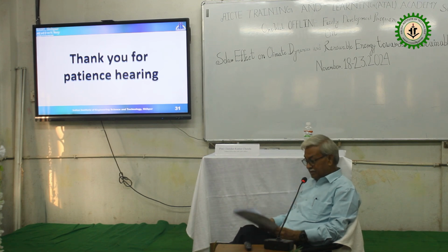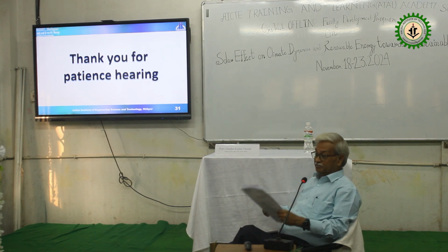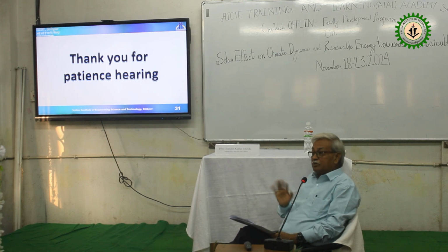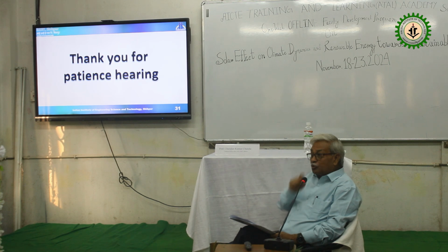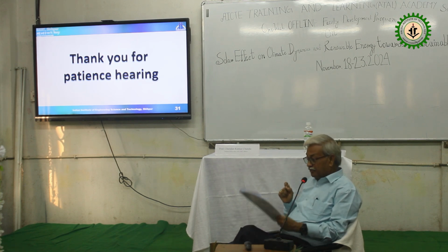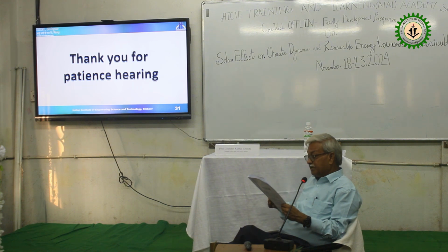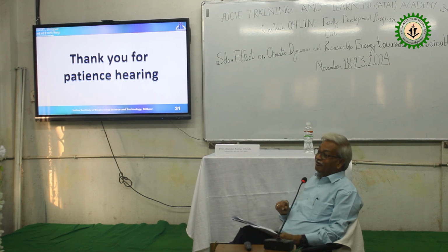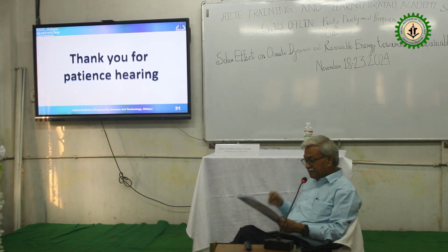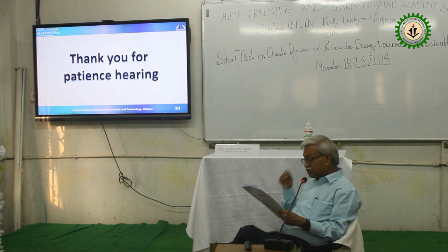Then the presence of transients, because in that disturbance we are not considering the noise and transients. At what speed does it occur? How long is the duration? So transients and noise in the frequency signal affect the accuracy of calculating the rate of change of frequency. So ROCOF is a very, very important issue in penetrating renewable energy. A lot of scientists and electrical engineers are working on different ideas on this. Another important issue is accurate estimation of inertia from all possible sources, like generators including synchronous generators, voltage and frequency dependent load, and virtual inertia from other sources.